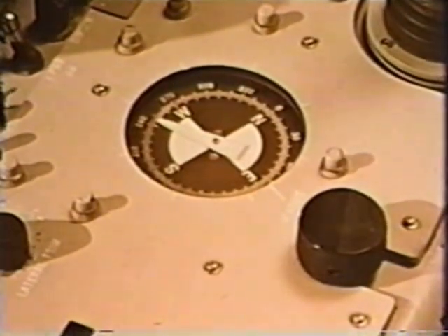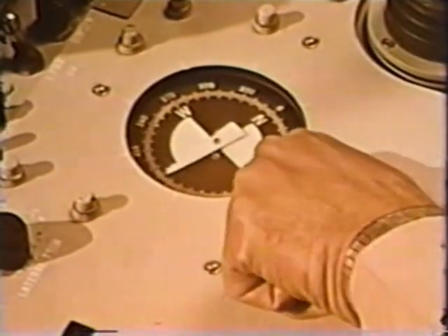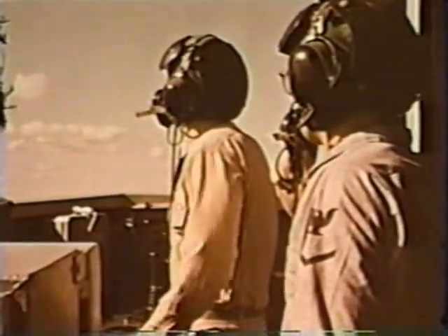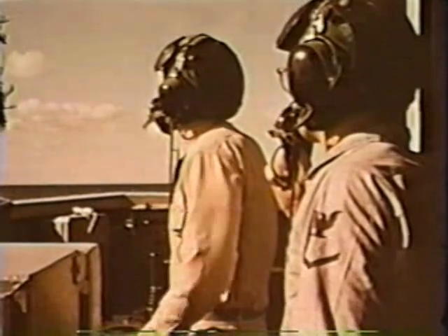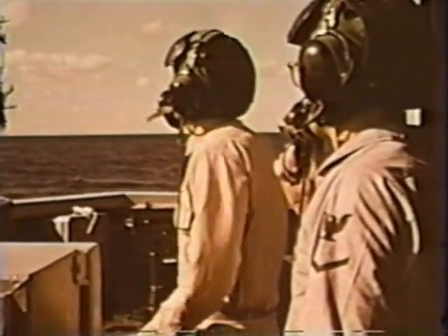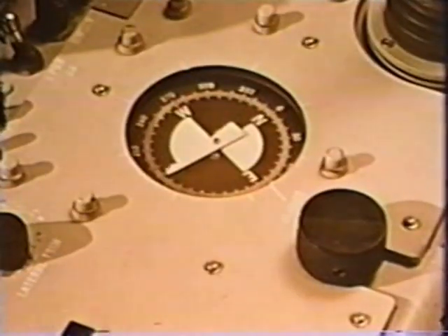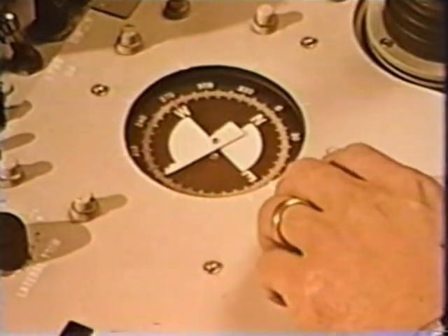The final approach should be made smoothly, with the relative wind off the bow. If it is necessary to make a large turn, the turn setting must not be changed more than 80 degrees at a time. A pause must be taken before making further settings for the remainder of the turn. Failure to use this procedure will result in a turn reversal.